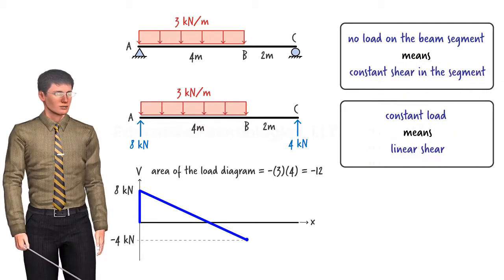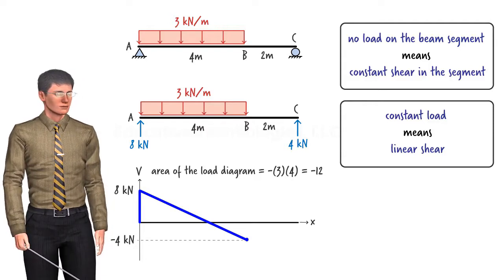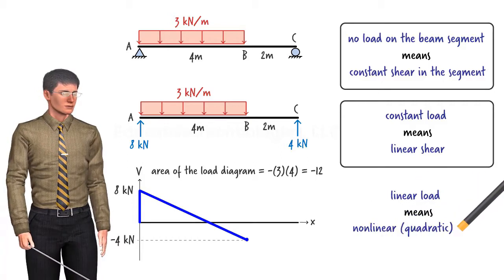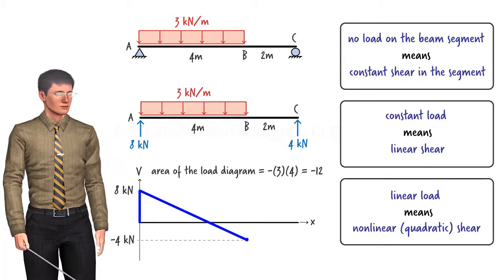What if the load was triangular? Then the shear diagram within the segment becomes a nonlinear curve representing a quadratic equation. A couple of exercise problems at the end of the lecture deal with such nonlinear diagrams.